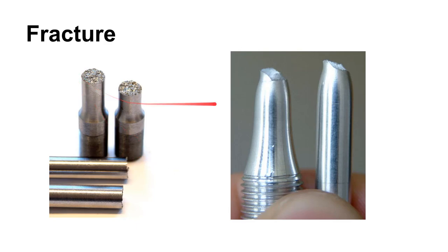All right, so you should be able to look at these two specimens here and determine which one is a ductile material and which one is a brittle material. Okay, so this is the ductile material. We see this necking, this elongation happening in this material. Over here, this is a brittle fracture. You see it's very straight along the sides, and if you were to measure the percent reduction in area, there really wouldn't be any. Okay, the percent elongation would be near zero on a material like this. We call this brittle fracture.